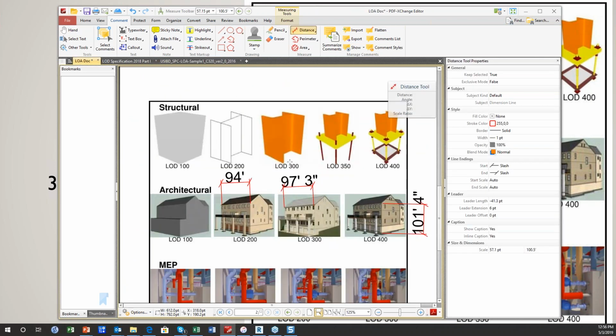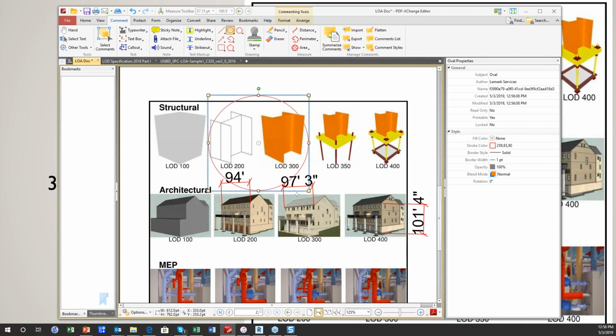The other one is what level of detail to ask for if you ask someone to model for you. My recommendation for most models is to aim for 200 to 300. This is your level of detail. It gives you enough that you can see the shape. It's not just an envelope, but you're not getting down to the nuts and the bolts of everything. Doing the nuts and the bolts is going to make your model cost 3 to 4 times what you can do if you do a level of detail 200 to 300.